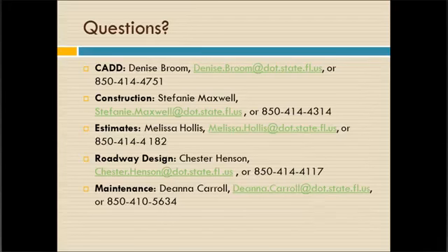So that pay item, 710-90, goes with thermoplastic, the 711? Yes, it does, because you'd have one coat of paint, and then that would take care of 710-90. Then you would have all of your 711 pay items that cover your thermo. And that's for the cure period, before they can lay the thermo. That's one coat of paint. Yes, that one coat of paint. I hope that clarifies it. We will get that one clarified in writing so that it helps everyone. It will be in the Q&A documents.